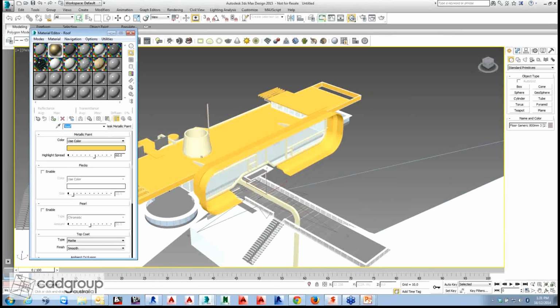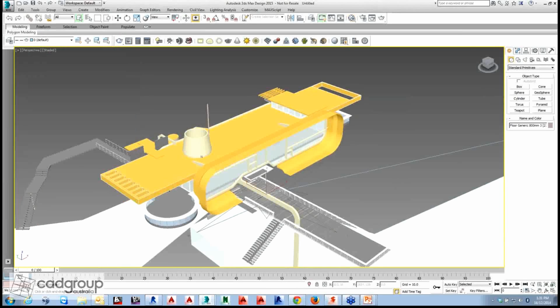And the advantage of using this suite workflow is it's a linked model. So if I have to make some changes, either I can do them within the 3ds Max environment or go back to the design software, which is Revit, change the models, and we can simply update inside 3ds Max using File Link Manager.